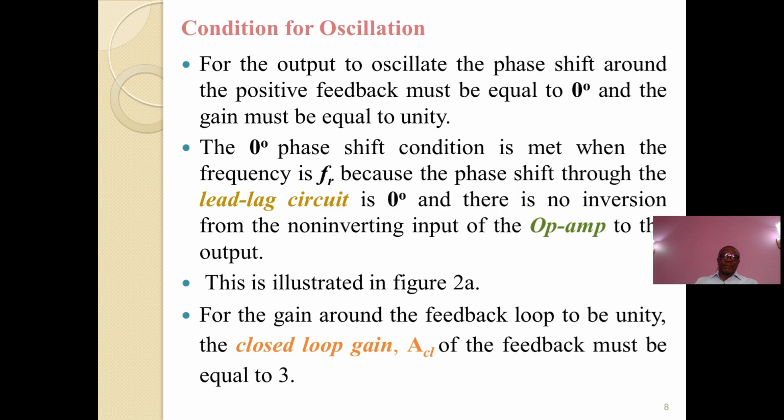So the 0 phase shift condition is met when the frequency is Fr, because the phase shift through the lead lag circuit is 0 degrees and there is no inversion from the non-inverting input of the operational amplifier to the output.